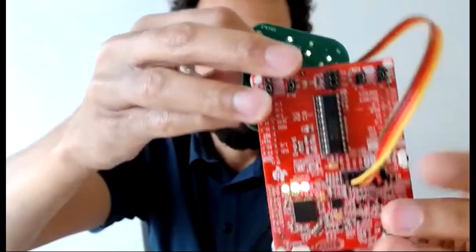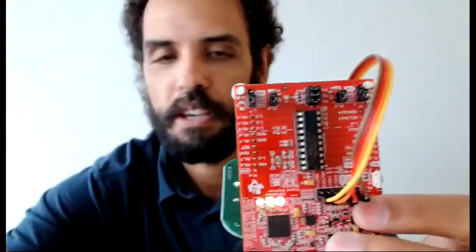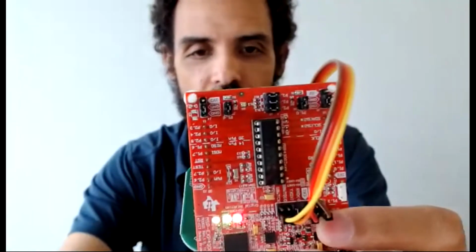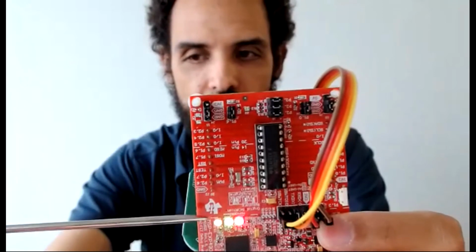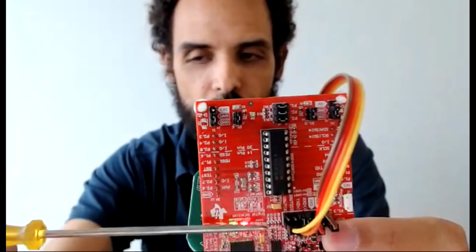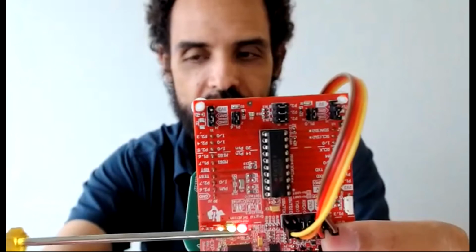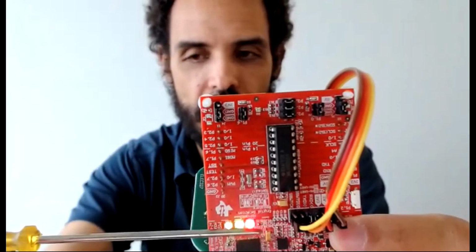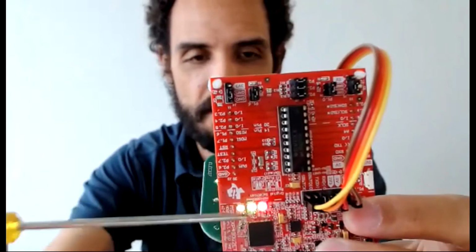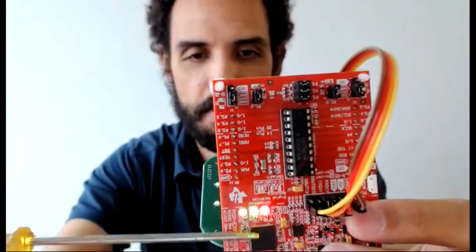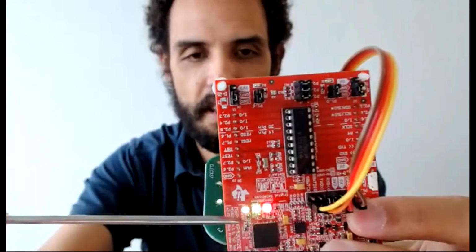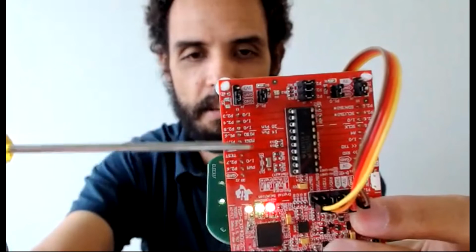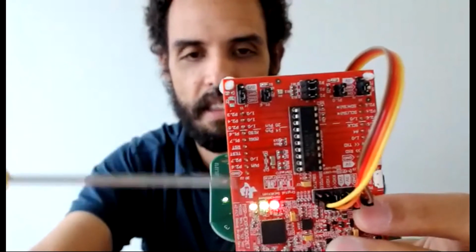Oh, and there's something important, which is that if you look on the PCB, you can see that the jumpers normally connect across these two pins, right? So you want to connect to the side of the jumper that's on the programming side, so this debugger system side, as opposed to the launchpad side, the MSP430 side. If you connect to the MSP430 side, you're basically connecting to nothing.